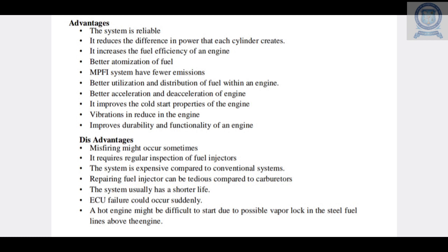Misfiring might occur sometimes. It requires regular inspection of fuel injectors. The system is expensive compared to conventional systems. Repairing a fuel injector can be tedious compared to carburetors. The system usually has a shorter life. ECU failure could occur suddenly. And the last final point is a hot engine might be difficult to start due to possible vapor lock in the steel fuel lines above the engine.